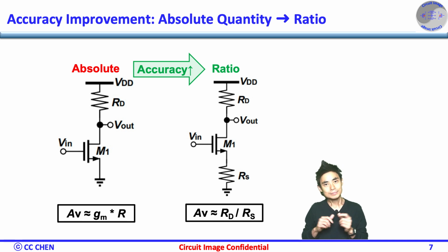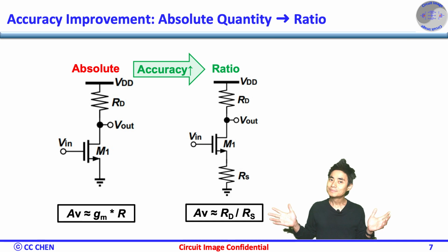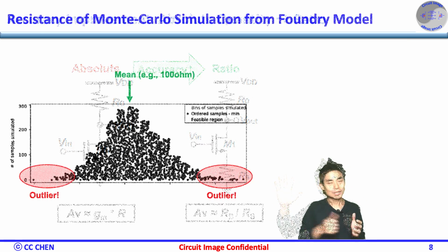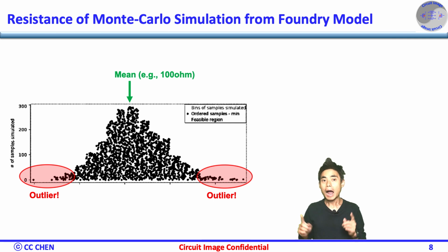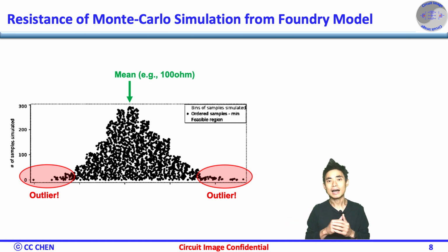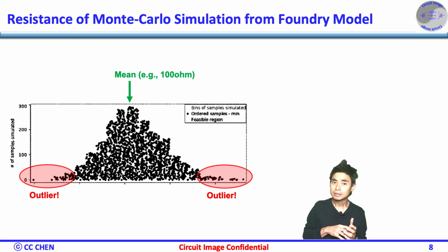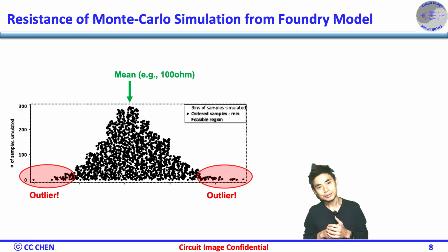If that's the case, why should I bring it up? Think about the high precision requirements for 5 seconds. Correct. If you are targeting a high resolution or precision, the target should be somewhere around 10 bits or even 14 bits. Unfortunately, it's very difficult to minimize the local variability easily unless we've done a special dynamic element matching, as in the DEM video.